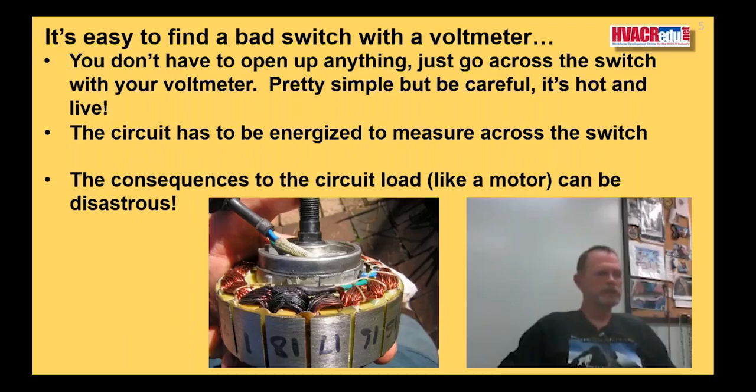What's the issue with a bad switch? A bad switch creates resistance in the circuit. A switch is not designed to be a resistance in the circuit. It's designed to be a conductor in the circuit. And so as you're looking for equipment, you're out there doing your job, you've got some questions about why something's happening, maybe you're replacing a motor because it burned up for some reason, you can't really figure that out. Look at all the switches.